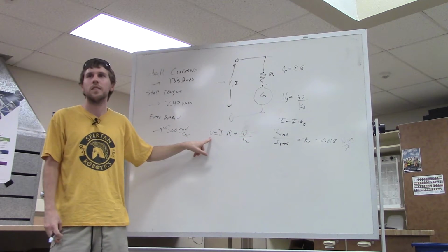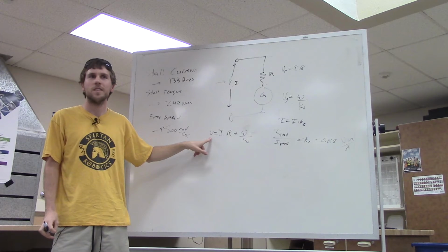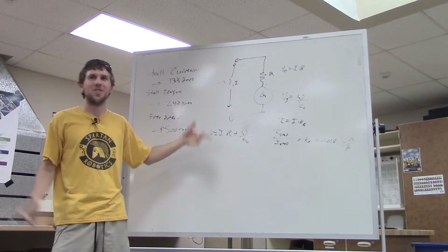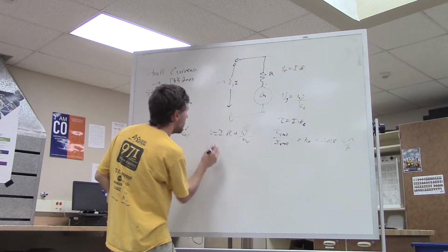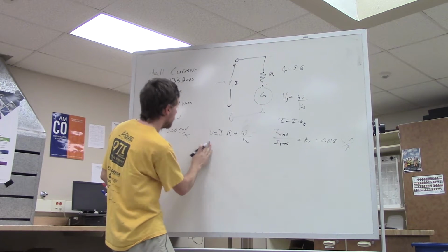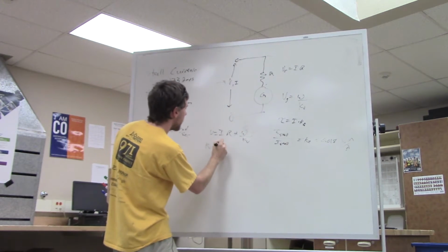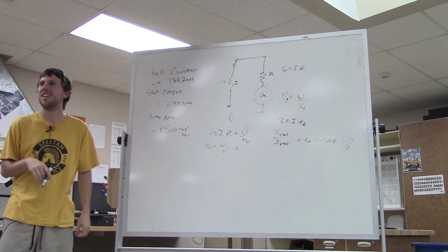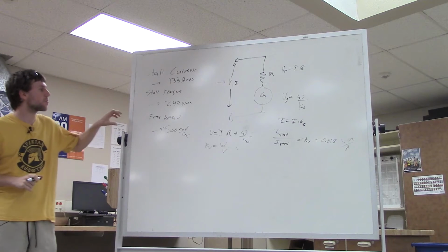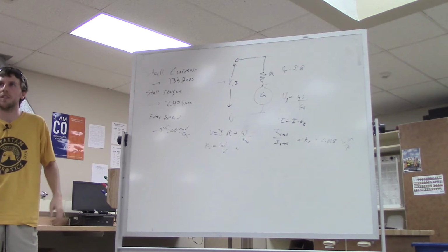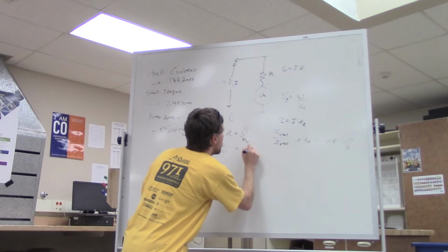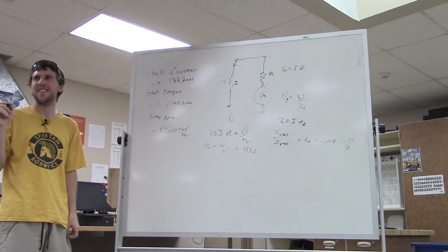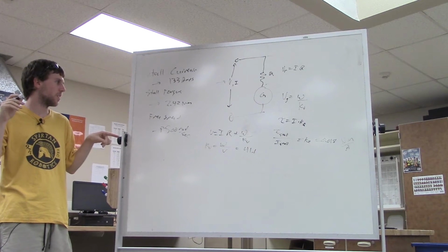What do we pick for voltage? Well, you pick whatever the spec sheet used, which in this case they rated at 12 volts. So it's 12 volts. I stand corrected. KV equals omega over V. This is about 500 radians a second. And units? Radians per second over volts. Yep.